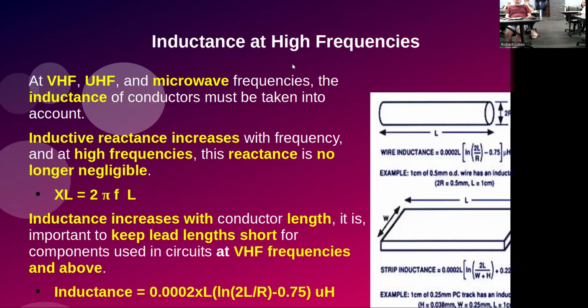So when we go up to really high frequencies, that's where the length of conductors starts to have an effect. Not only the inductance, because the inductive reactance goes up with frequency, but the length of it can affect the phase shift.